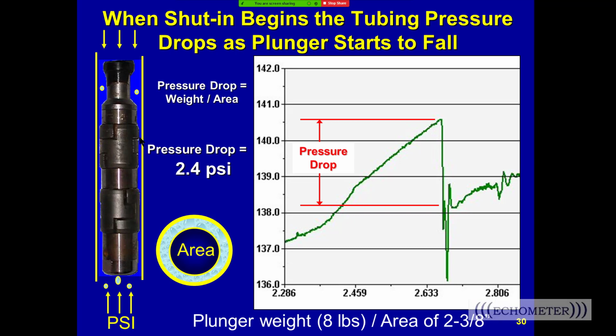It comes up dry because the shut-in time wasn't long enough, or there's some kind of restriction in the tubing. So before you can really know what to do, you need to track the plunger and make sure it's getting to bottom. And then if it's getting to bottom, then you need to increase the afterflow time to bring in more liquid and reduce the energy in the well.